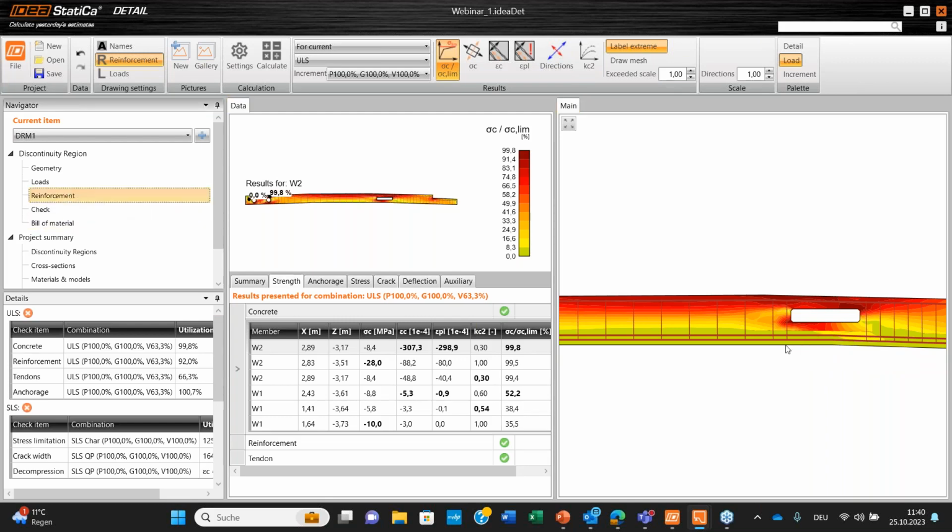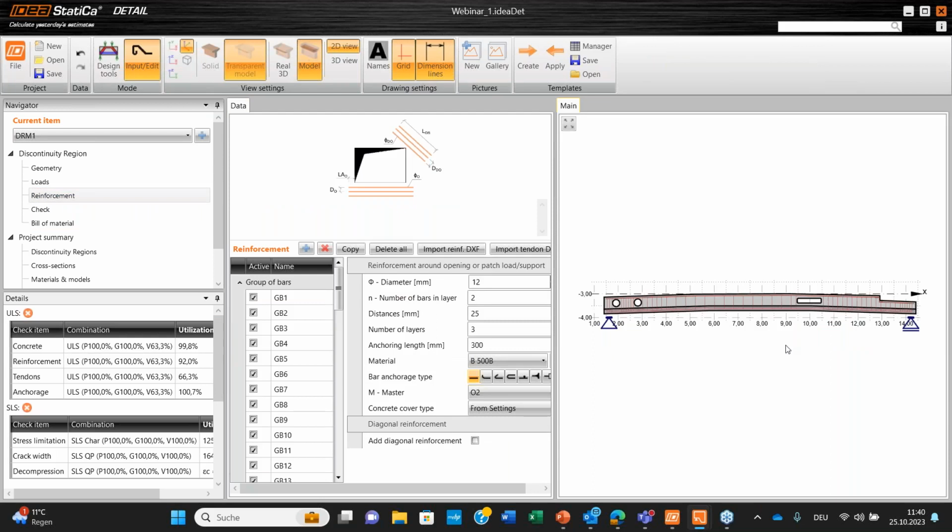If at the end of the procedure you are satisfied with the rebar layout, a cool feature is that you can right click and send your system to a DXF, and then you send the DXF to your draftsman. It means that you don't need to prepare rebar sketches. It takes time, so you can save time with it.